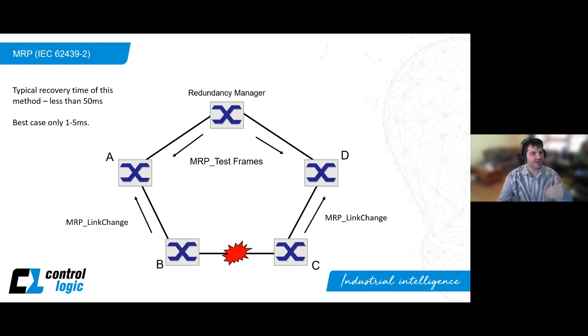The other advantage MRP has over HyperRing is that HyperRing uses VLAN 1 always. It's hard coded, you can't change it. So any network with HyperRing or multiple HyperRings has to have VLAN 1 across the entire network for correct operation, which gives you a single point of failure. MRP supports customized VLANs, so you can choose which VLANs are used for each MRP ring, and it's recommended to make them all unique. This means that there's no common failure VLAN, if you will, across the entire network or infrastructure.